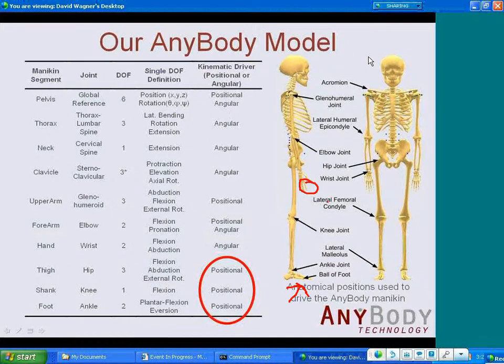And so we ended up changing some of the angular data to positional constraints with regards to the joint centers that we had, and did that as an incremental process, just to make sure the model was always able to run and not kinematically indeterminate or kinematically infeasible. That provided us a method for changing the model and developing our own.